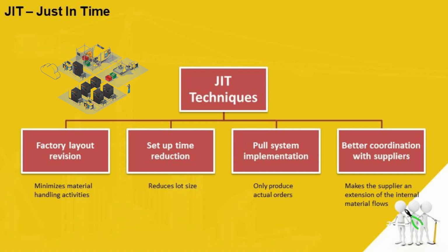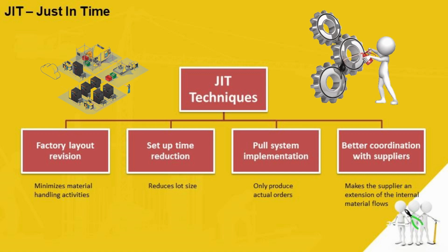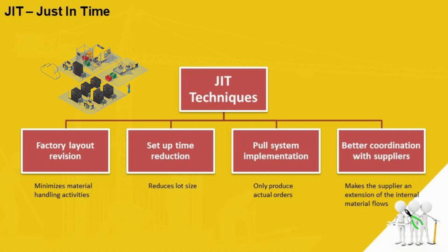Now, in setup time reduction, factories can reduce setup times in order to reduce lot sizes and smooth production. Reduced setup times enable a factory to produce smaller lot sizes, which are economically viable. Smaller lot sizes enable a factory to produce a broader variety of products, assemblies, and parts each day. However, preventive maintenance and lower defect rates also need to be achieved.